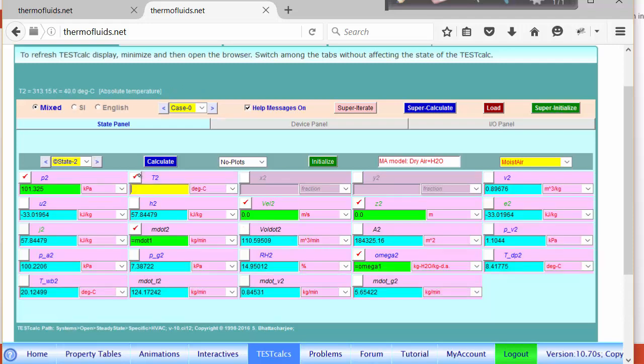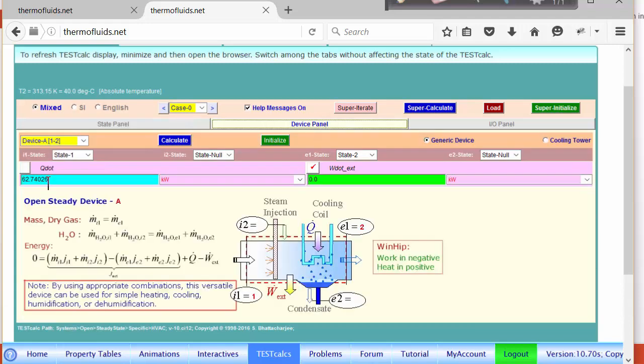So if I make it, instead of 40, 25 degrees Celsius, so we'll say, you know what, if I heat the air half the way, then how much power do I need? 62.77 kilowatt or half of that? Our guess pretty much will be half of that, right? Instead of raising the temperature by 30 degrees, we are raising it by 15 degrees.